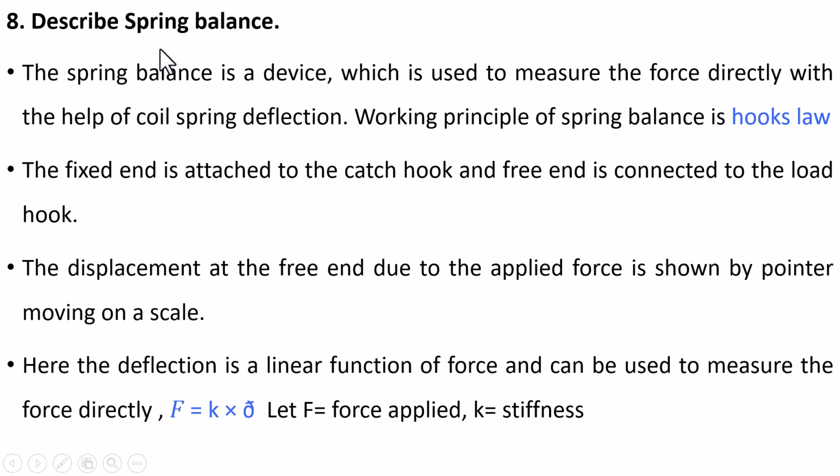Describe spring balance. The spring balance is a device which is used to measure the force directly with the help of coil spring deflection. The working principle of spring balance is Hooke's law. The fixed end is attached to a catch hook for holding it, and the free end is connected to the load to be measured, or load hook. The component whose weight we have to measure will be hooked to the load hook.